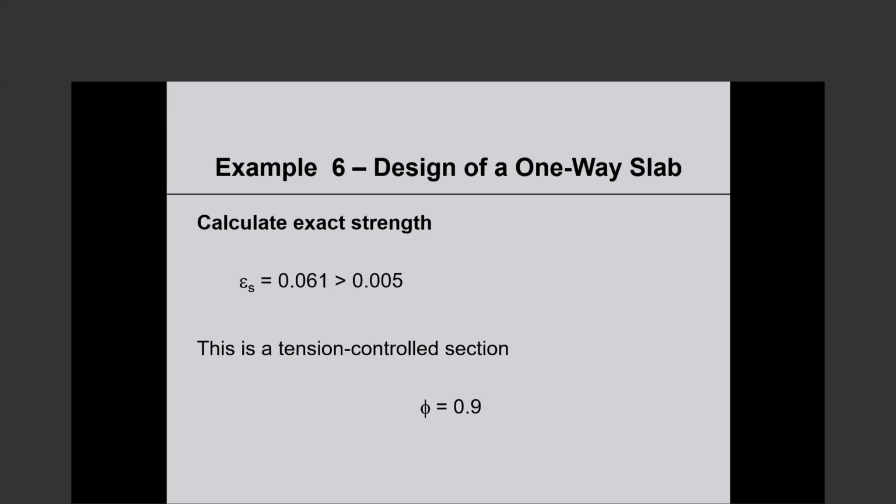It is, so you consider a cracked section. That does not mean you use the cracked moment of inertia, which is a fraction of the gross moment of inertia. You use the effective moment of inertia.